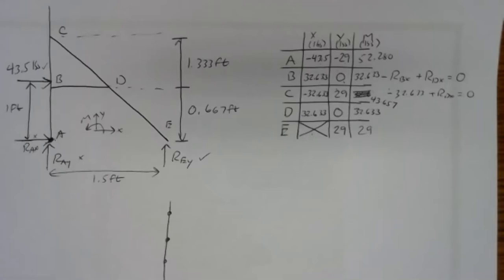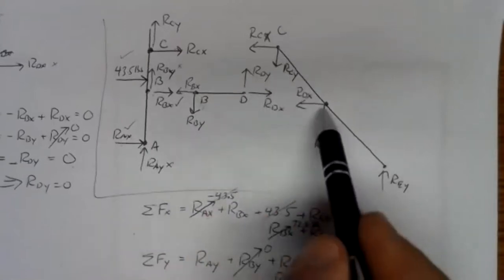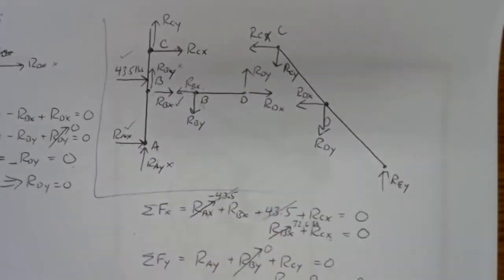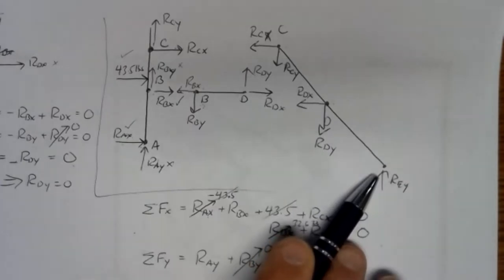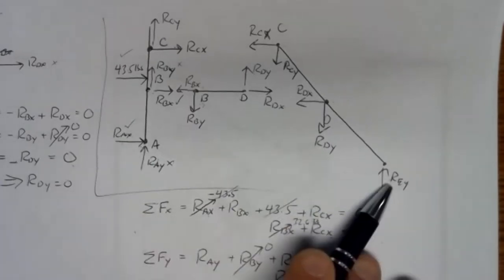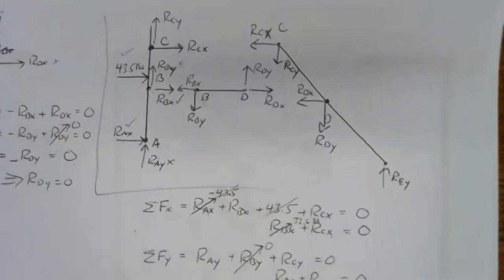The only little quirk that we have to be aware of is that Newton's third law issue in dealing with the free body diagrams. You got to make sure you've got consistent information between free body diagrams. The only values that stay the same as your original assumptions are those external supports. But you do this flip-flop thing on the internal joints, on the joints that are joining members together, not members and supports.